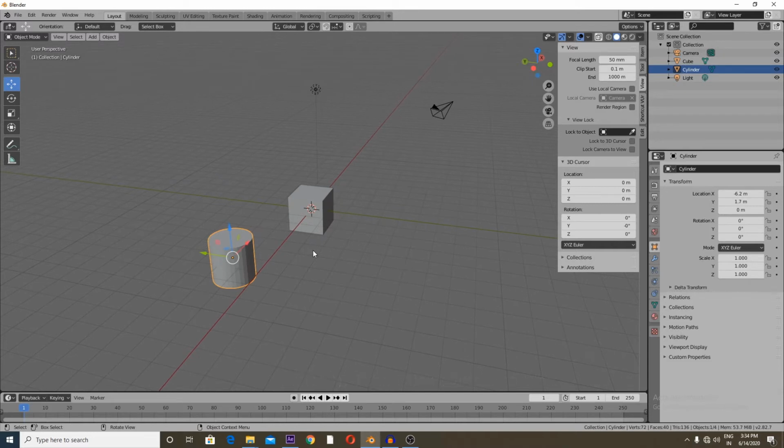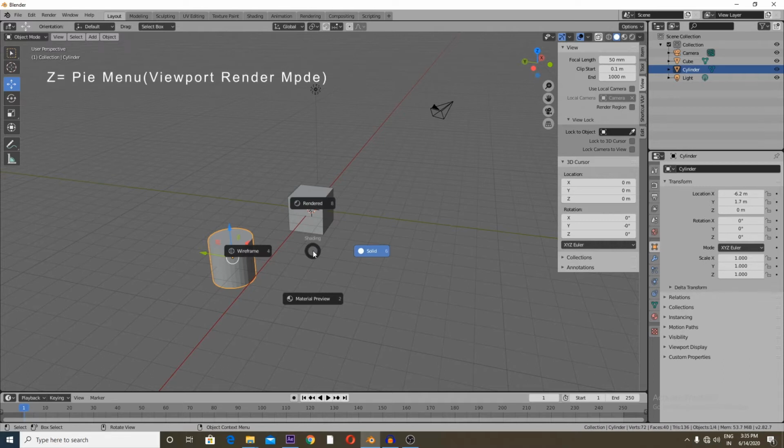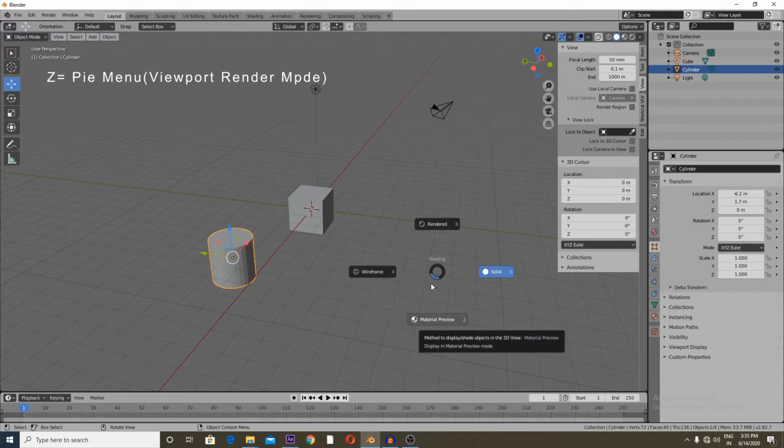The next very important thing is the pie menus. What are pie menus? Each pie menu is associated with a hotkey. Suppose I have pressed the Z key on your keyboard, you can see in a circle there are different options initiated with it. If I don't want to choose any option right now, I will right click and stay out of it.